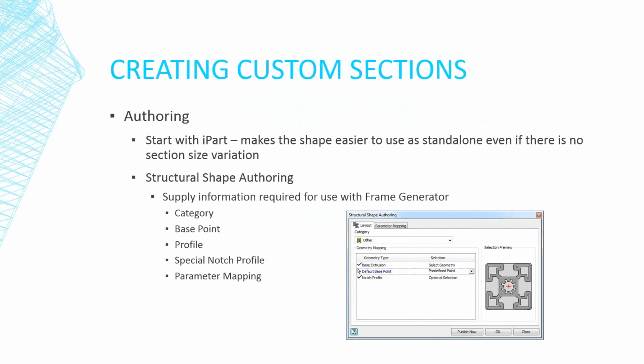You're going to want to create an iPart out of that, and add at least a few sizes that you're going to use, maybe right into the iPart. And then later on you can add additional sizes in the Content Center. We'll be covering that a bit later.